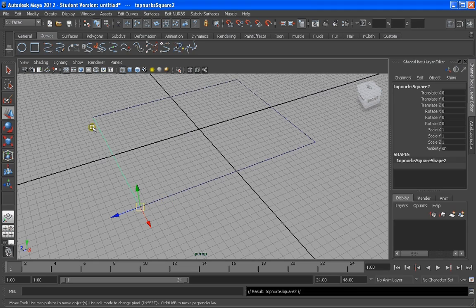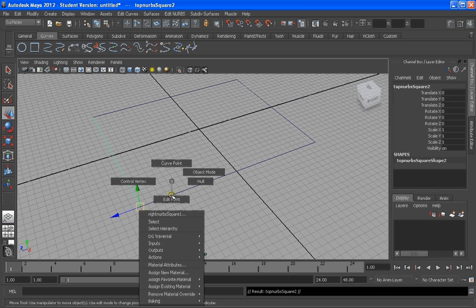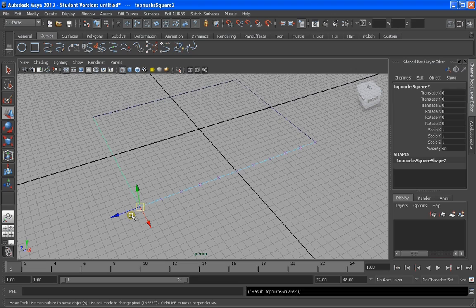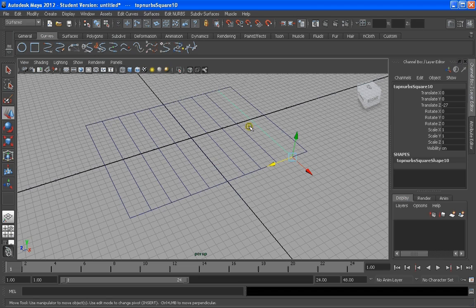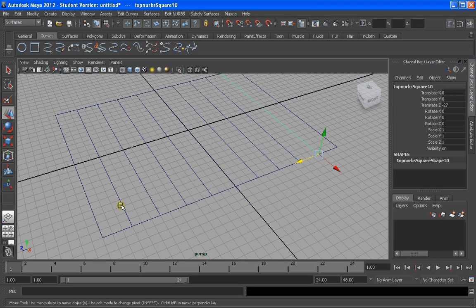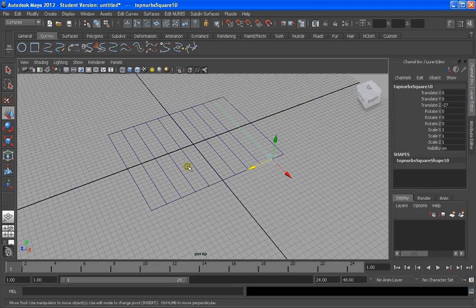I'm going to Control D to duplicate this line, and right click on this line and say edit points, and as I move it in this direction pressing this arrow, I want to press V and it will snap to this point. Now remember, if I do Shift D now, it's going to do the same copy and transformation a number of times. So if you cannot do that step, it's basically you did something else between the Control D, which is the duplicate, and the movement. You did something else, and it's just the program doesn't remember if you didn't do it straight forward.